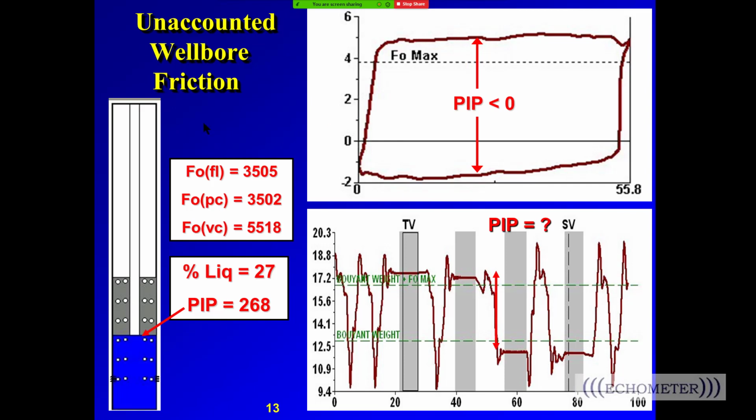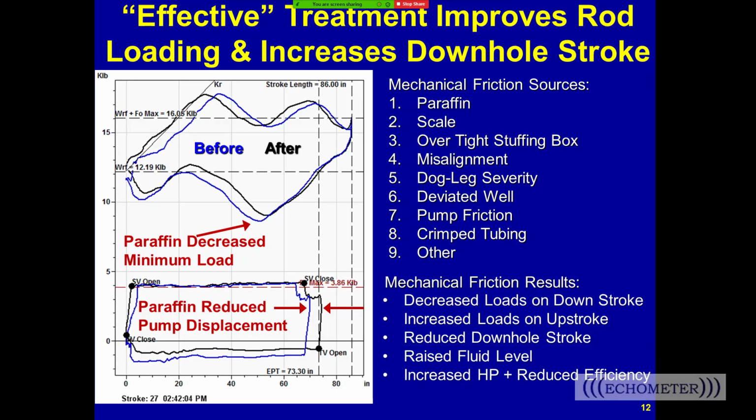So you can either use hot oil that doesn't have any paraffin in it, because then it has room to absorb the paraffin as it moves in the well, or you can use hot water with a crystal modifier or a paraffin solvent. Those would be my recommendations. But you shouldn't use hot oil from the bottom of the tank, for sure.